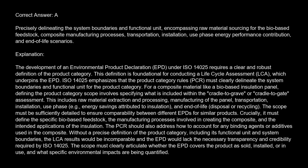ISO 14025 emphasizes that the product category rules, PCR, must clearly delineate the system boundaries and functional unit for the product category. For a composite material like a bio-based insulation panel, defining the product category scope involves specifying what is included within the cradle-to-grave or cradle-to-gate assessment. This includes raw material extraction and processing, manufacturing of the panel, transportation, installation, use phase, e.g., energy savings attributed to insulation, and end-of-life disposal or recycling. The scope must be sufficiently detailed to ensure comparability between different EPDs for similar products.